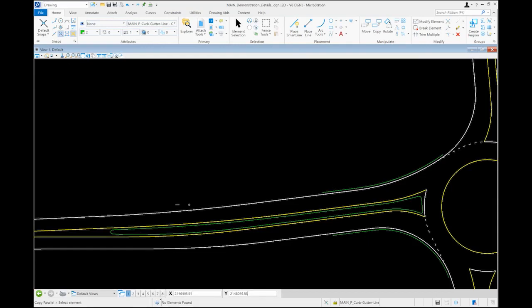In some cases, your outside curb line may end up being longer than your splitter island, and in this case, we'll likely end up with a splitter island that's quite a bit longer than our outside curb line. The outside curb line is going to be driven by some different practical design considerations, vertical design, drainage needs, as well as what might be needed to support your fastest pass speed control and channelization coming into the roundabout. Some other considerations are whether you're tying into a closed section where you have drainage inlets or whether you're transitioning into open drainage swales along the roadside.